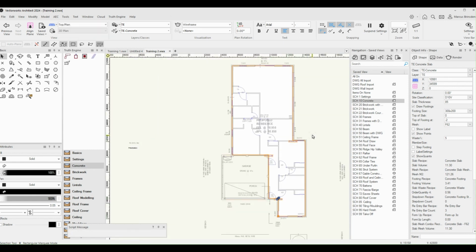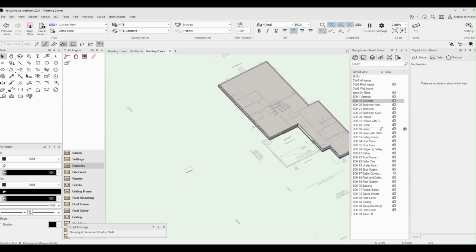And you would also use that for an example where basically one edge of your slab is different, or one footing is different to the others. It's easy just to turn it off, then you can draw all the footings manually around your slab. Another thing you can do with the slab tool is create a form up or a step footing. So if we tick, okay, so now we can draw a step footing.